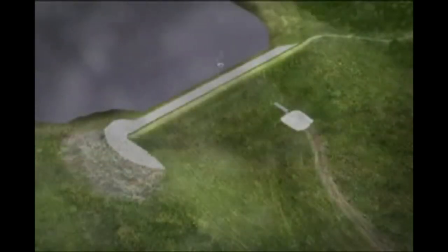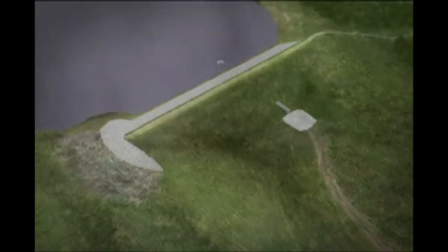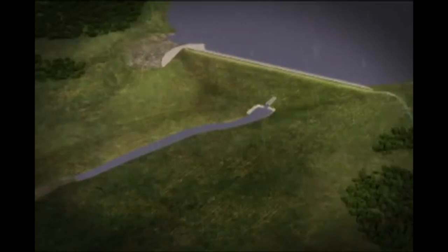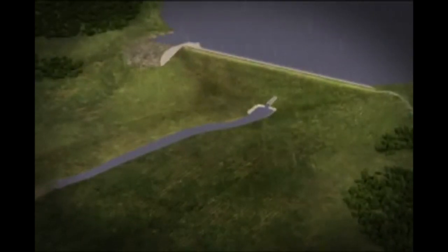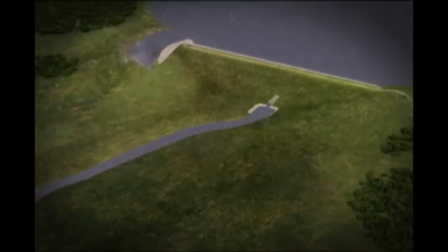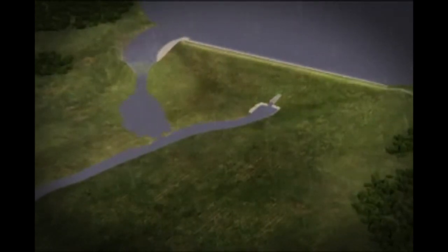Dams are designed to store runoff resulting from heavy rain. When storage has reached a specific limit, spillways are designed to pass the excess floodwaters, initially through a primary spillway. Many dams are equipped with an emergency spillway to help pass large flood inflows which exceed the capacity of the primary spillway. In an extreme flood, flows can exceed the combined spillway capacity, spill over the top of the dam, and create a very dangerous situation.